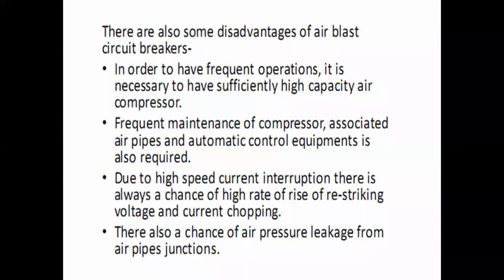No doubt there are some disadvantages of air blast circuit breaker. In order to have frequent operation, it is necessary to have a sufficiently high capacity air compressor. I had already told you that in an air blast circuit breaker, in order to provide the high blast of air, we require an air compressor. With its help you can generate high pressure air, but for generating high pressure air you require a compressor. So it will include extra cost and extra equipment.